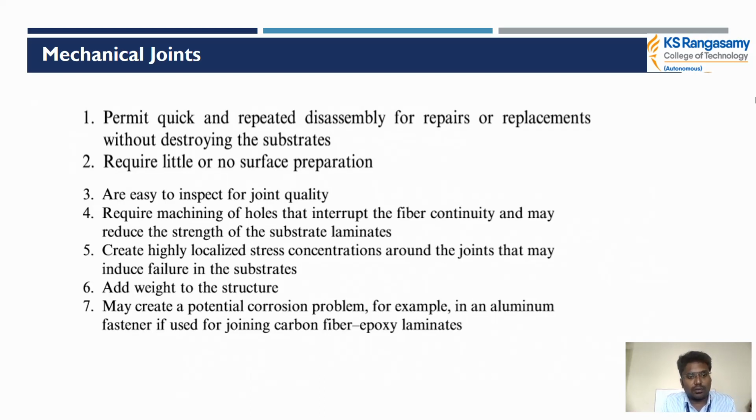And the fourth one is that machining of the hole interrupts the fiber continuity and may reduce the strength of the substrate laminates. It also creates high localized stress concentration around the joints, which may introduce failures of the substrate. So these are the major points for the mechanical joint.